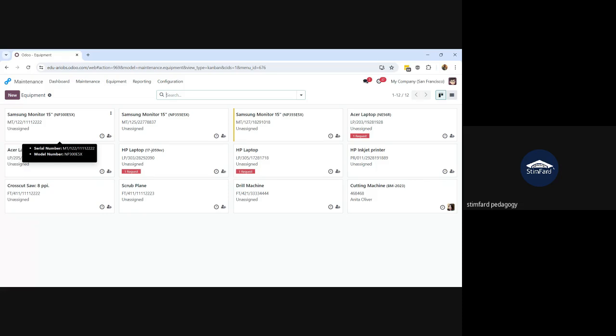Other than that, over the passage of time, after 3 years, let's say the machine has become old, and now you are getting more maintenance requests, so you have to change the maintenance schedule. You can change it according to the machine's usage and the details of the maintenance requests from your engineering team. So it all depends upon the machine manual and the machine historic data, how the machine is working. So you can plan according to that. Okay.